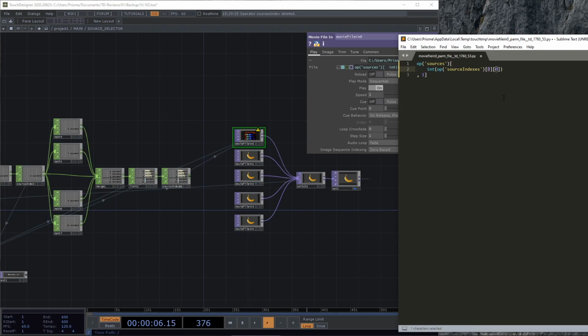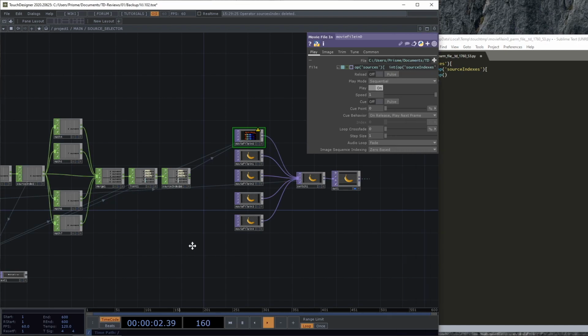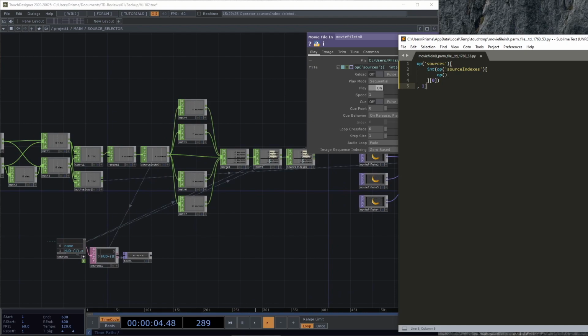We're gonna do it step by step, just as always. So first we're gonna select the active input value. So that would be op active input. There's only one channel, so 0, and always one sample as always, so 0.